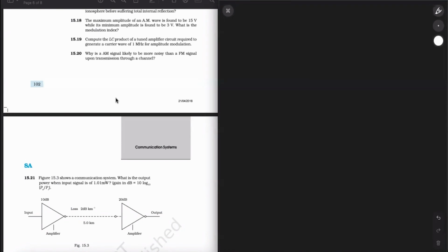So during the transmission, noise can also be added and the receiver assumes the noise is a part of the modulating signal. But in case of FM, the frequency of the carrier wave is changed as per the change in the instantaneous voltage of the modulating wave. So noise does not affect the FM signal; simply we can say that noise signals are difficult to filter out in AM reception, whereas FM receivers easily filter out noise.